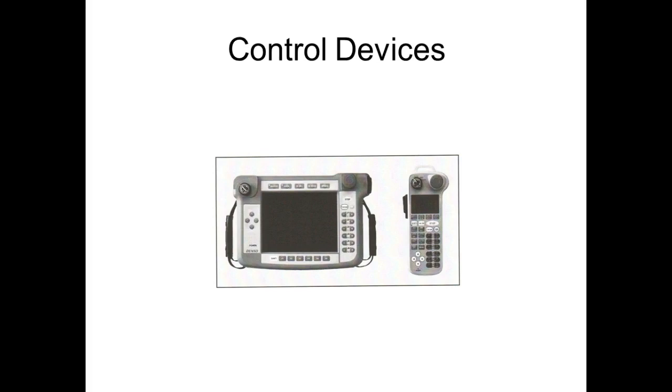And what's nice about it is that if I'm trying it out over here, and my robot's still running the old program, it's no problem. If I go over there and I upload it, it doesn't work quite right, it's okay, right? I can just go back to the old program and come over and play around with it. So offline programming is really, really neat. But it all depends on the accuracy of the model.